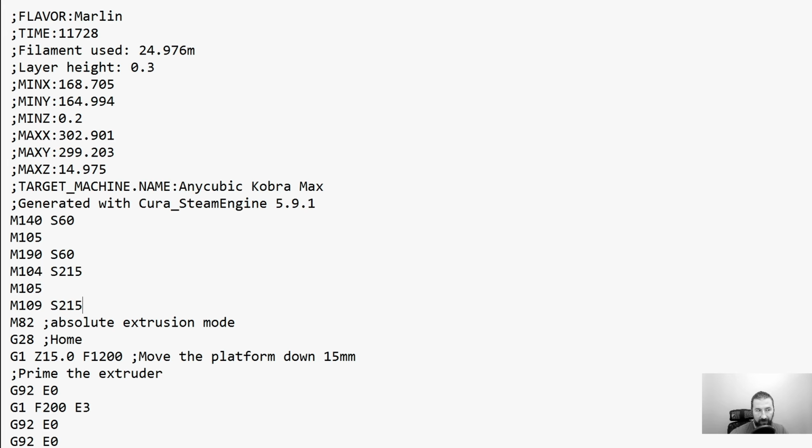Sometimes tool changer commands also vary from machine manufacturer to machine manufacturer, because some 3D printers use a standard CNC G-code command for tool change, and some other machines use a macro for that because they need to perform some more actions, like extrude something, clean the nozzle, etc., before the actual change command. So these might differ, but the first thing you do if you design custom G-code is look into your normal sliced file and try to separate these sections first.